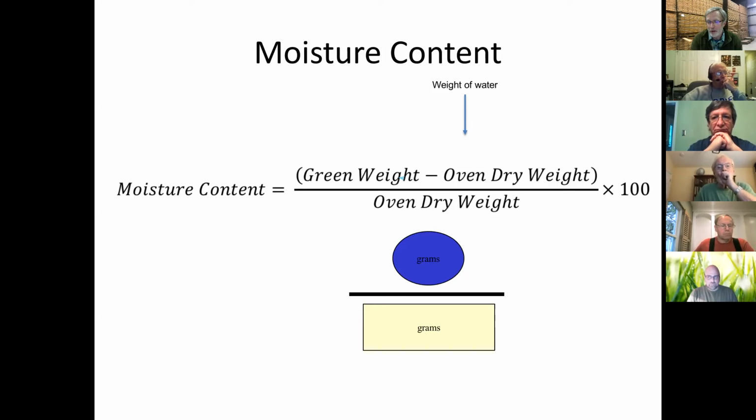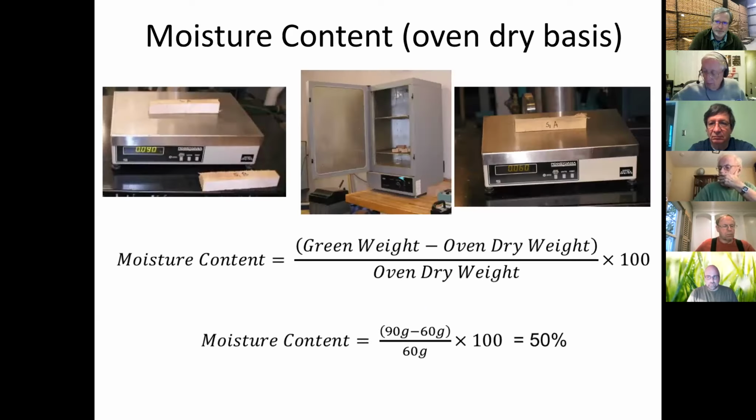The dry mass of wood, or the amount of water that was contained in the wood? The amount of water contained in that volume would be significantly greater in weight than would the oven dry mass. So species like southern yellow pine, when you first cut a southern pine tree down, the sapwood commonly has a moisture content over 100%. Most species do not. Most species, your oaks and your yellow poplar and most of your hardwoods, typically have moisture content somewhere between 65 and 85% when you cut the tree down when it's alive and growing.